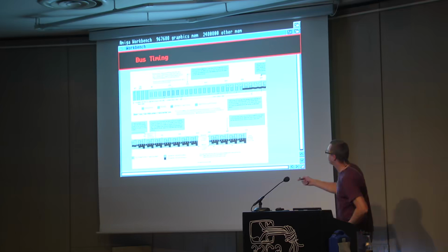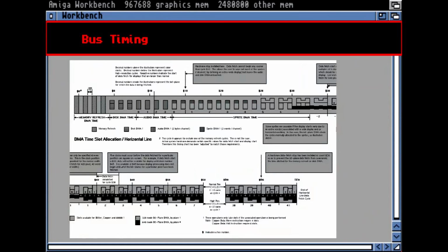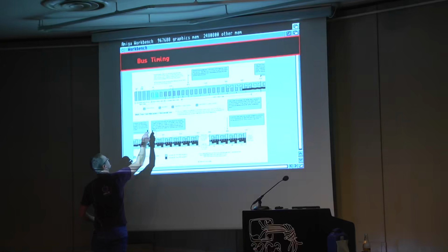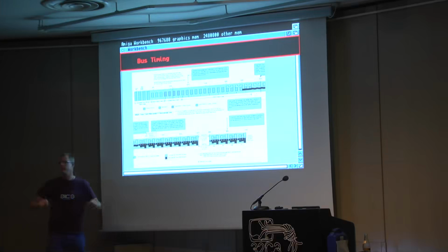What we see here is time slots. So here the gray, and here, and here, and here. Every slot is one bus cycle where whatever device could access the bus, okay? And the timing was made in such a way that the even cycles, this is an even cycle, and this, and this, and this, were used by the CPU.